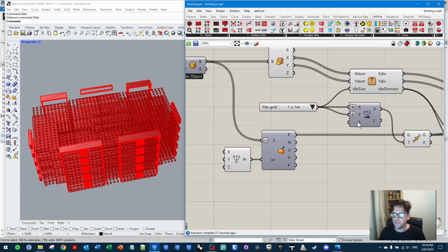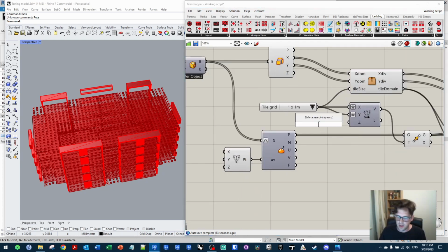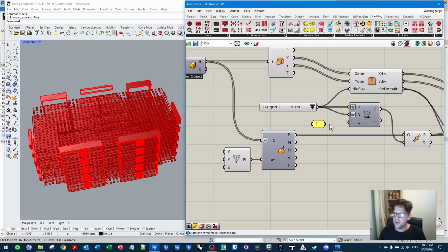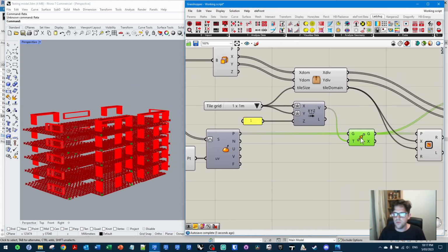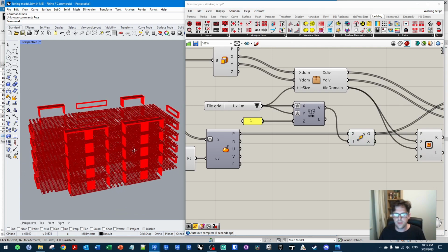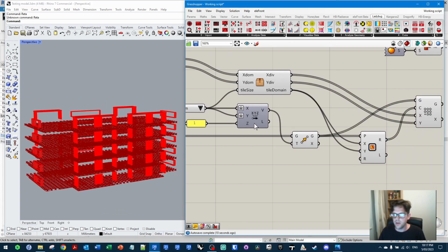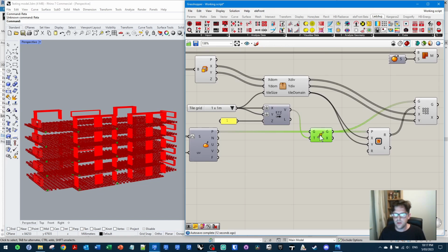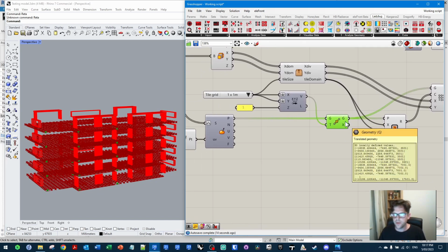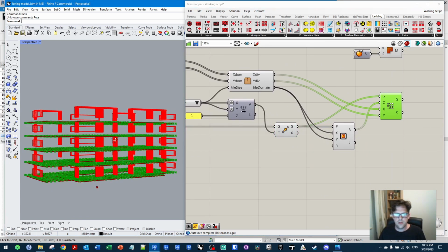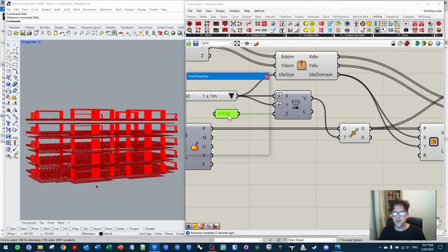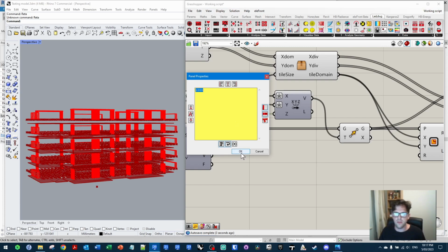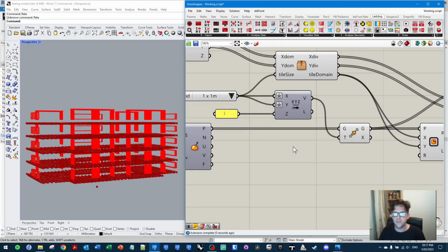So that's pretty handy. Now, I might for now actually just move these up by 1 meter. We need these points to sit above in this case. So that should now move those. I'm just checking. Doesn't look like it's moved them up actually. Interesting. Of course, because it's 1 or 1,000. So there we go. It did work. So we need to be just the tiniest bit above the mesh. So I'm just going to use the number 1 in this case.